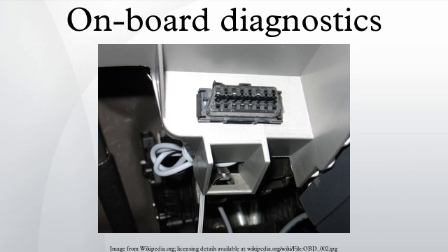The pinout for the ALDL connection on these cars is as follows. For ALDL connections, pin 9 is the data stream, pins 4 and 5 are ground, and pin 16 is battery voltage. An OBD 1.5 compatible scan tool is required to read codes generated by OBD 1.5. Additional vehicle-specific diagnostic and control circuits are also available on this connector.